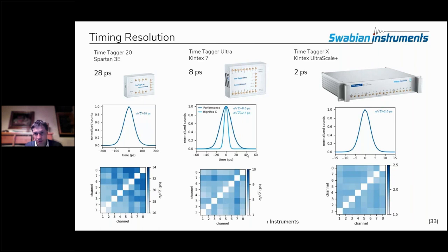And by the way, to measure these data, what we've done is simply take a square wave, put it into a power splitter, hook that up to 2 inputs of the Time Taker, and measure multiple start, multiple stop correlation. And these are the curves plotted there, and on the bottom, these are really all pairs of channels against each other.